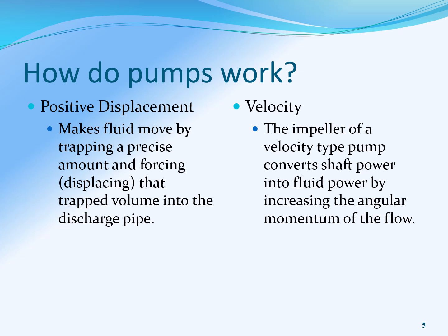So how do these work? You've got a positive displacement pump that makes fluid move by trapping a precise amount of water and forcing, or displacing, that trapped volume into a discharge pipe. You've heard of positive displacement meters, and so it's generally the same. It's a measured amount of water that is used repeatedly and flows through, in this case, a pump.